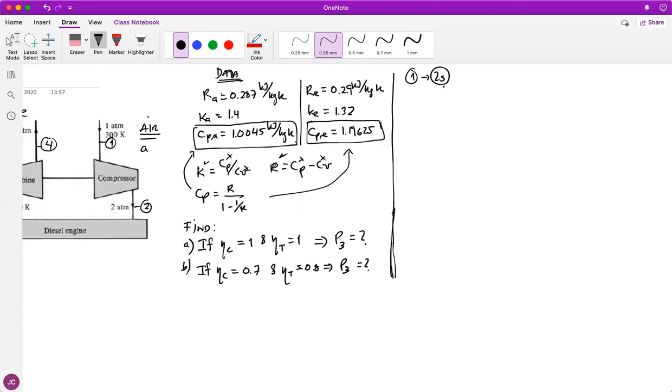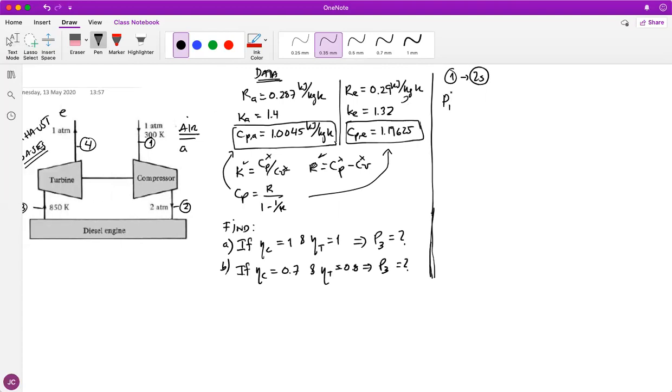So for an ideal gas, I can write this. P1^((1-K)/K) T1 equals P2^((1-K)/K) T2s. Why did you put T2s? Because what I want to find over here is what is the temperature if the process was isentropic. That's what I'm telling you. So what I'm doing here with that equation that I have below here is just this. I have put the isentropic part, which is the same thing as putting P1V1^K equals P2V2^K. Okay, it's the same thing that I have put down there.